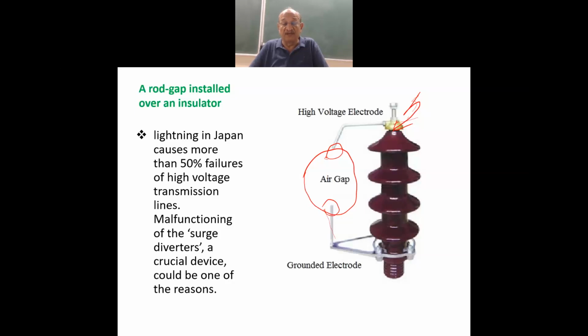When the flashover occurs, the peak of the traveling wave is grounded, but since it is traveling, it is able to proceed further as a traveling wave, with an attenuation in its maximum magnitude.